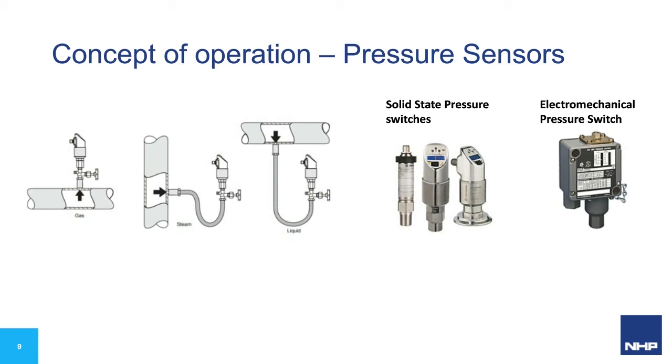Now, with solid state pressure switches, the pressure changes are measured electronically and output transistors activated based on the programmed settings. Now, when being set, you ensure you set maximum pressure rating for the contacts to cut out and select a differential which indicates how far below your set point you want your contacts to cut out also.